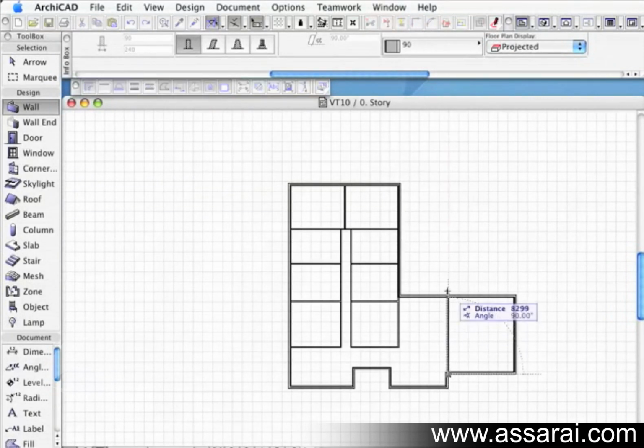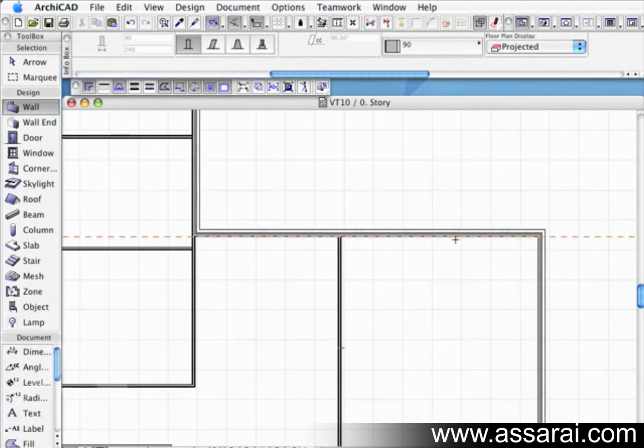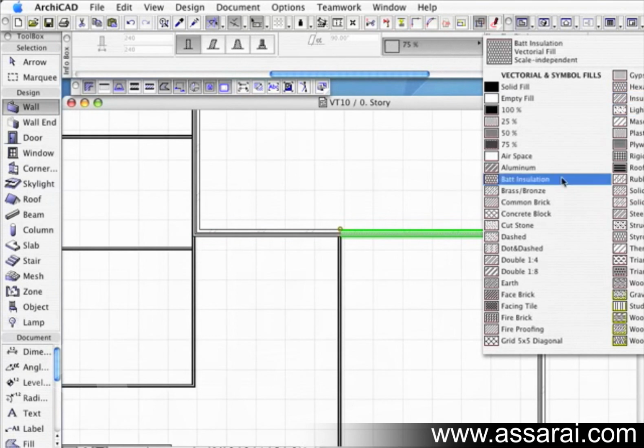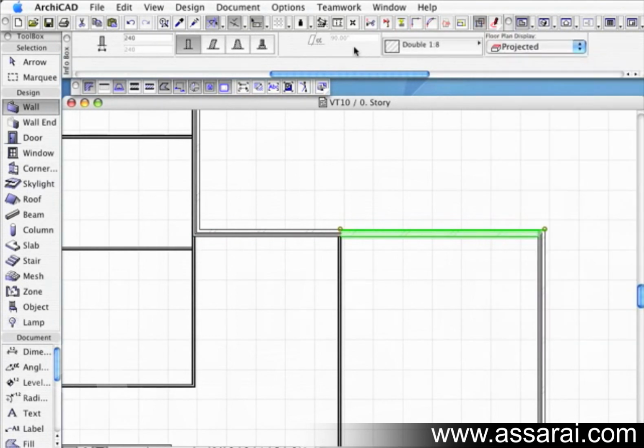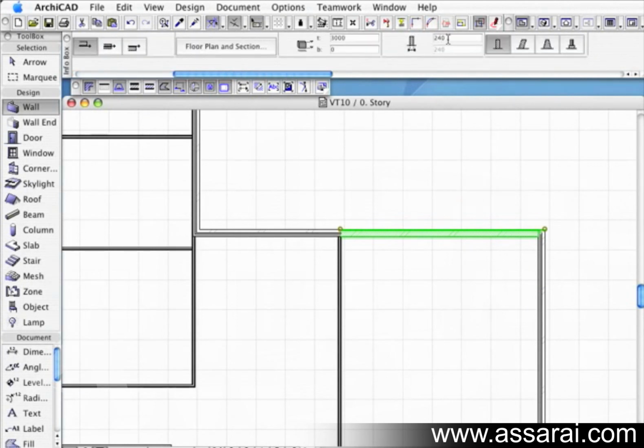Then I might need a wall going up here, so which means this wall here wouldn't be brick veneer anymore, could be a solid brick wall. So I click on the axe tool. Now the guides come up there, hold the shift key, the eyes ask me which side do I want selected after I split it. So now I'm just going to change that to a single brick skin wall. I'm going to change the thickness of it to 110. That's a 110mm brick wall.